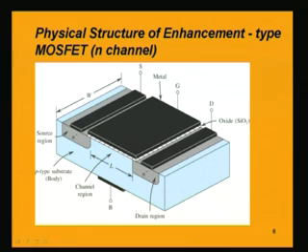So, here as we see, there is a P type of substrate, which is the body of the MOSFET, and there are two N regions. Here they are shown as N plus and N plus. Plus is to mean that it is a heavily doped N region, and we will use minus for lightly doped N region.